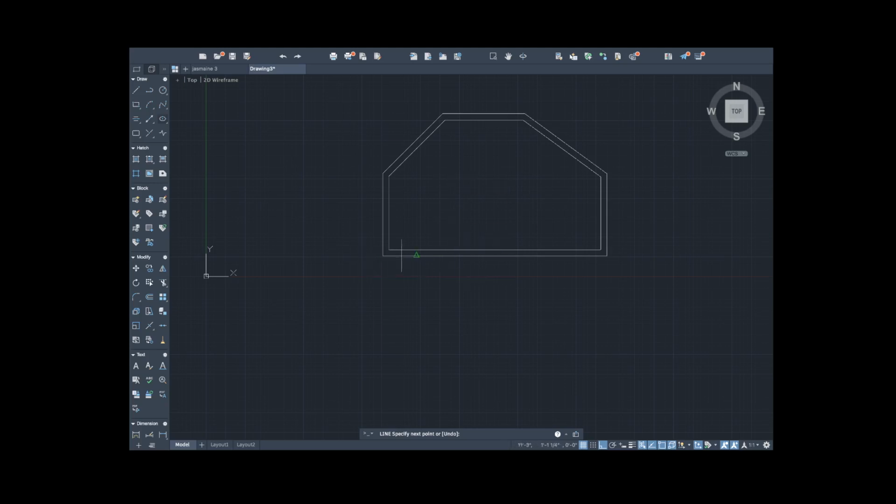I'm gonna go up, and I started from the outside. This one, on the outside. So I'm gonna go up. I did not come out of my command. I'm gonna go 3 and 7¼ again. So 3 feet dash 7.25 of an inch. Press enter, and then if you go left or right, it should form a right angle. So I'm gonna bring this line here, then I'm gonna do another one there, and then another one going up. Okay, then I'm gonna escape.